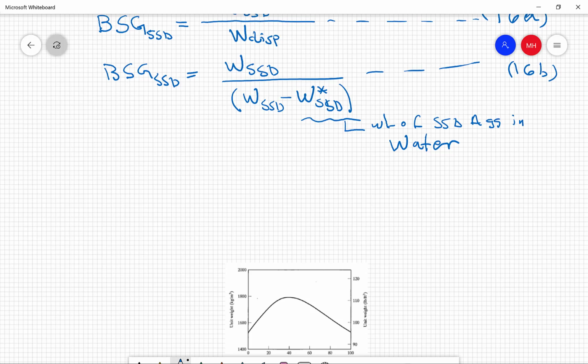So this quantity is actually measured experimentally, since the aggregate attains the SSD condition before the measurement is complete. So this is always true for wet aggregate, but could be an error or incorrect if the aggregate is very dry and absorption is slow, which is not the usual situation, by the way. So it's not the case.